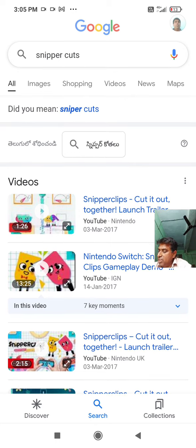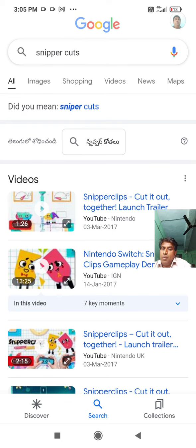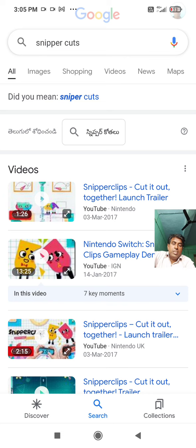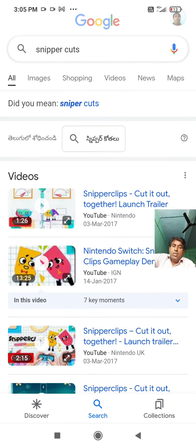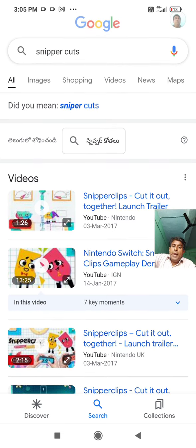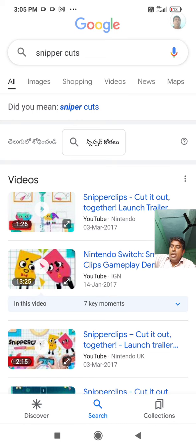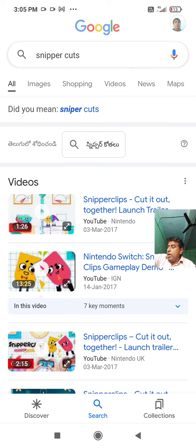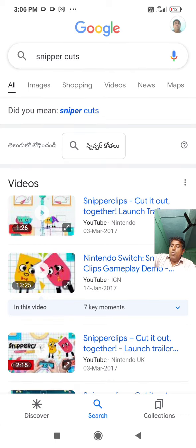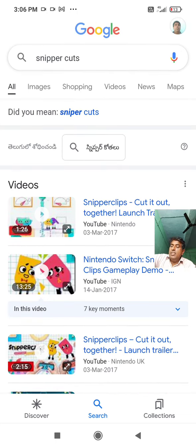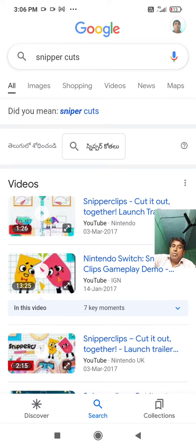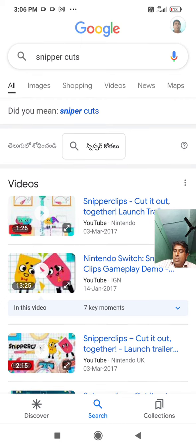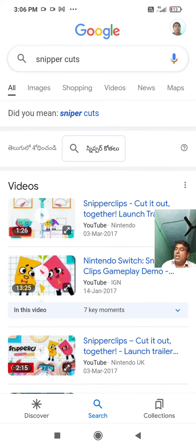After that we went to cutting, and in the cutting section of in process inspection we have seen frayed edges, serrated edges, ply to ply fusion, single edge fusion, pattern precision, notches, drilling. So I am telling one more time, in the cutting we have looked for frayed edges, serrated edges, ply to ply fusion, single edge fusion, pattern precision, notches and drilling. So this is in the cutting section.